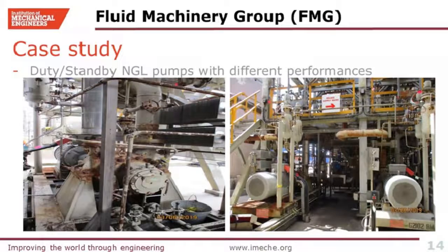The arrangement is 200%, so only one of the pumps is in service at a time, which means the pumps are not running in parallel. Vibration levels on both pumps are well within the limits, but suction and discharge pipe routes are not exactly identical. Pump A has a couple more bends in suction compared to pump B.